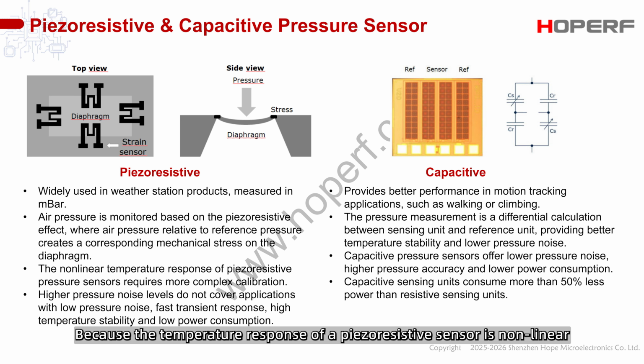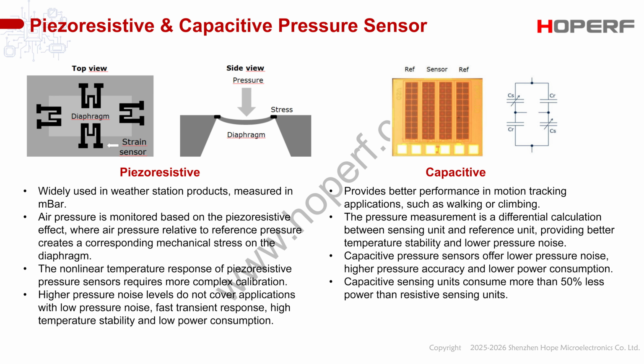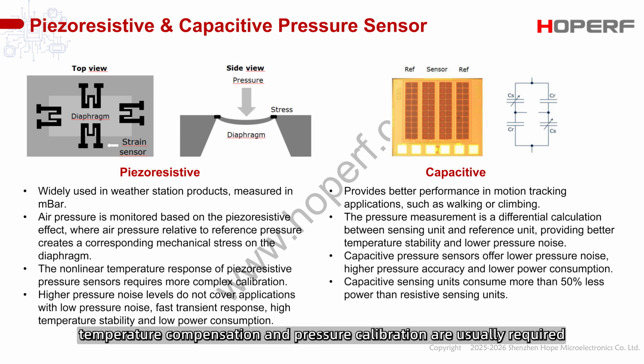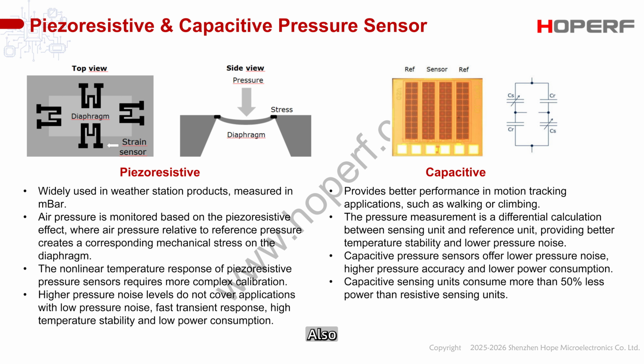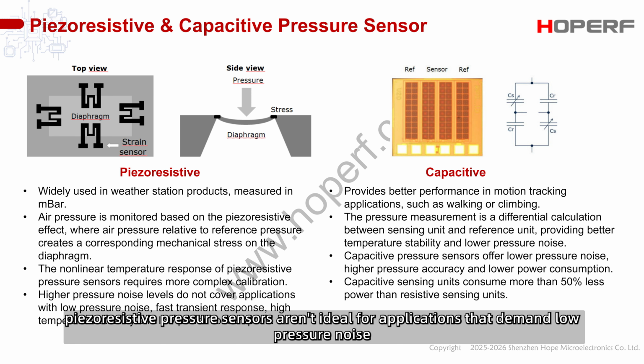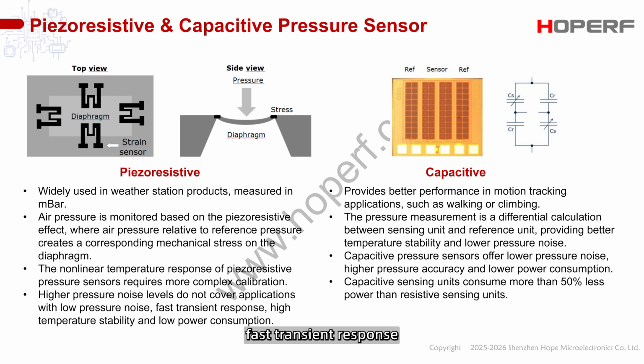Because the temperature response of a piezoresistive sensor is non-linear, temperature compensation and pressure calibration are usually required. Also, piezoresistive pressure sensors aren't ideal for applications that demand low pressure noise, fast transient response, good high temperature stability, or low power consumption.